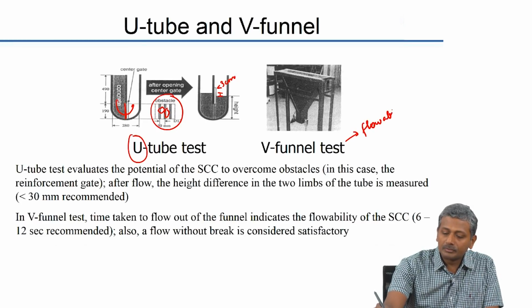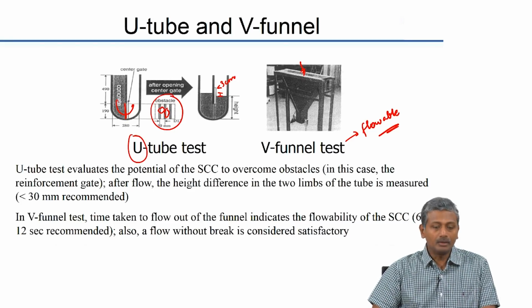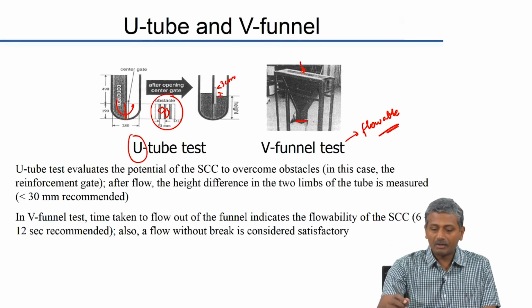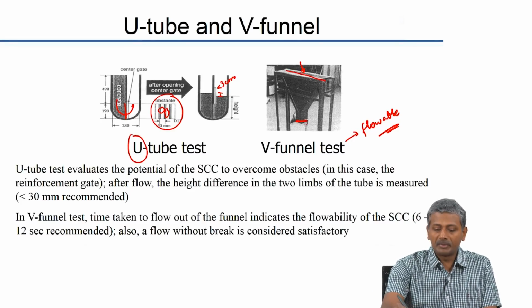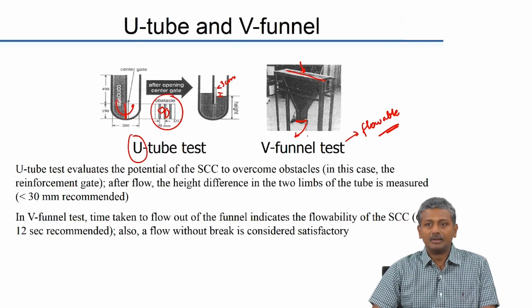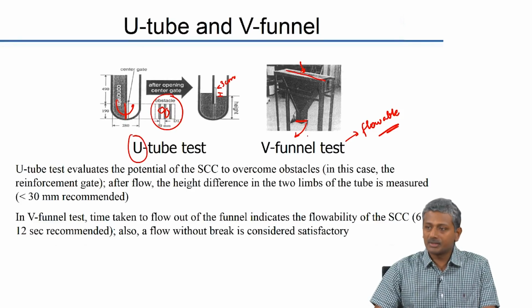Now, here you pour the concrete into this V-shaped funnel, the gate or trap door at the bottom is first closed. Okay. After the concrete is completely filled, you open the trap door and then allow the concrete to fall through the funnel. So, again if you imagine if it is water, it is going to fall almost immediately, it is going to come out in a single stream.